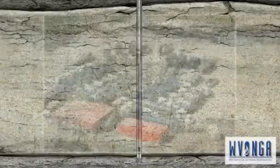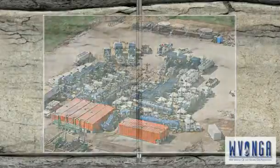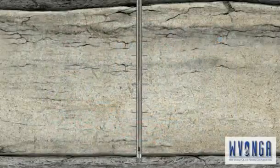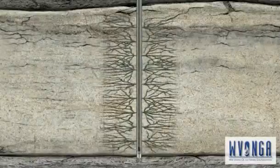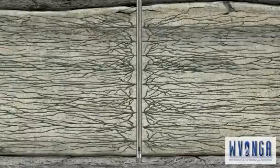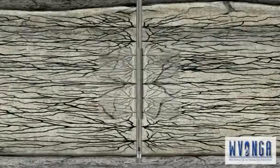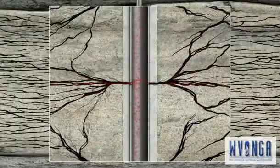The next step is to hydraulically fracture, or frack, the zone. Here, sand or other proppants are pumped into the wellbore under extremely high pressure. When the mixture reaches the target zone, the pressure forces it out through the perf holes and out into the sandstone formation, causing it to fracture. This creates a fairway connecting the reservoir to the well, inducing the released gas to flow to the wellbore.